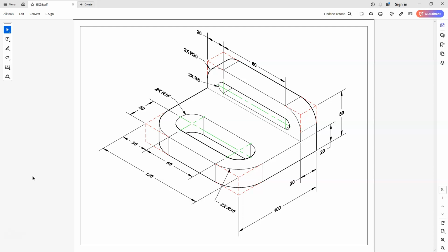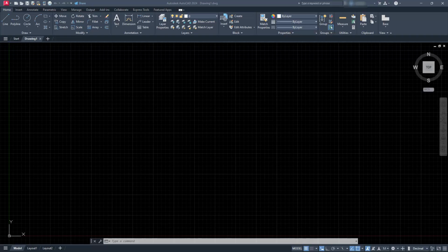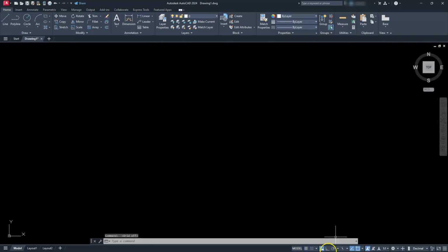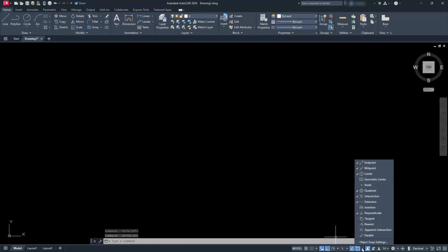All right. So remember that in order to do this, we actually have to have the 3D part, or we can do 2D isometric. But I'm going to create this drawing just the way you see it. Okay, so let's go ahead and do some of our normal stuff that we usually do. Let's turn our grid off, put the ortho on, and take a look at what running O-snaps I have turned on.